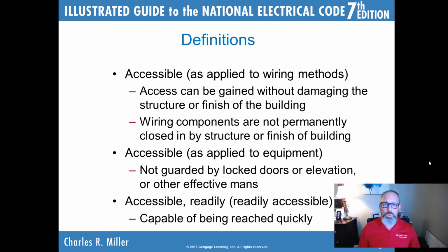So newer homes, you're not going to find these major electrical issues. Where I've seen them the most is in older homes that were built in the 1940s and 50s and 60s. And people have done additions. Over the years, they've added parts of the house, and in the process may not have had a qualified electrician. So you cannot put a box in a wall and drywall over it. It's very tempting when you're doing remodels, or a contractor might think, well, let's just go ahead and cover it up. Well, you need to get access to it.